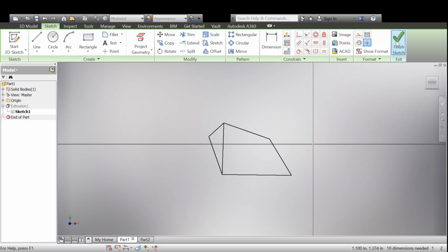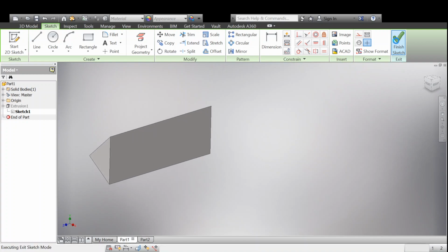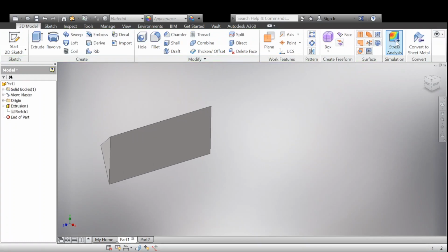So the triangle was here a minute ago, this was the original shape, and that was extruded outward. All I've done is change the triangle slightly, and the extrusion that we had there changes itself. So the extrusion went from looking like this to being cut into a smaller triangle because I physically went into the sketch that's contained within the extrusion and edited it.